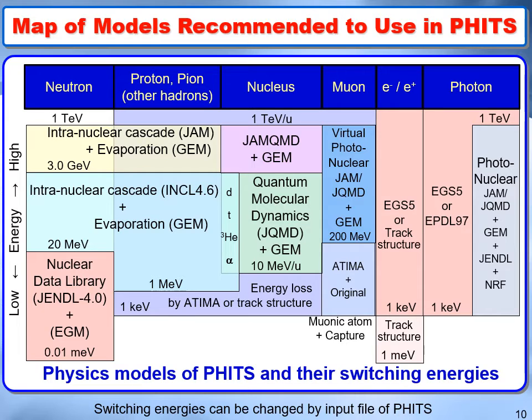Here is the map of models recommended to use in PHITS. There is no perfect model that describes all interactions caused by varieties of particles over wide energy range. Therefore, PHITS combines several models and data libraries depending on particle type and energy.